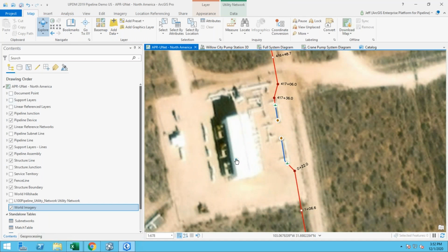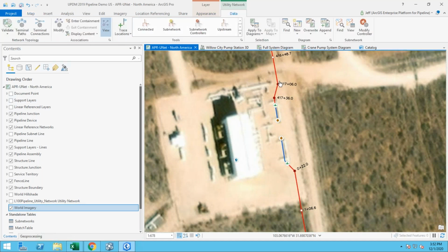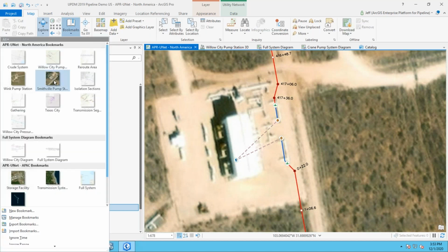And again, I can create these objects where they exist, and then using the utility network connectivity, define my linear referencing here to the mainline valve, which has some non-stationed pipe inside that launcher receiver assembly, and then create a connectivity association between the end of that pipeline over here to this pump or compressor and back out the other side. So now I've got linear referencing and a fully connected model in and out the other side. Or maybe I know some more stuff in here, but I don't know where it is spatially. So I can start to lay out more of a schematic view of those facilities as well.